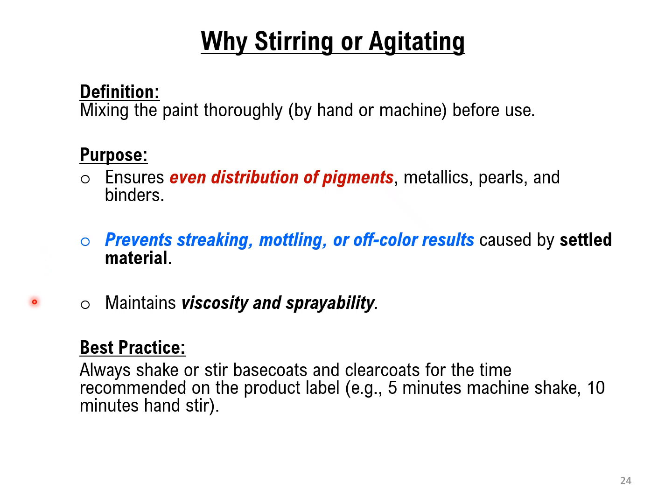It helps in maintaining viscosity and sprayability. The best practice is to always shake or stir base coat and clear coats for the time recommended on the product label. It could be 5 minutes machine shake or 10 minutes hand stir.